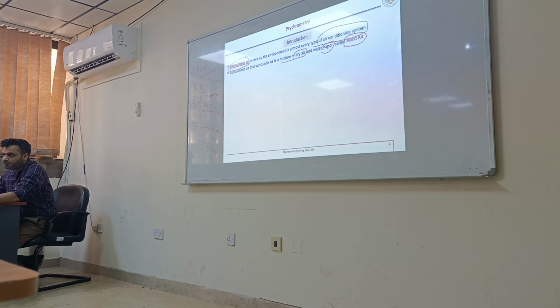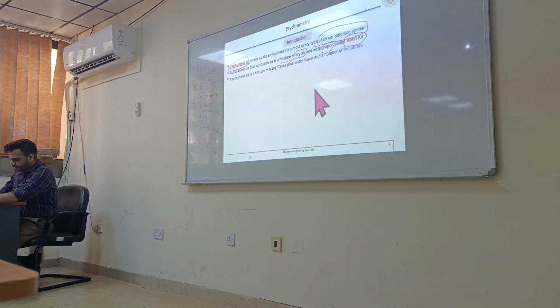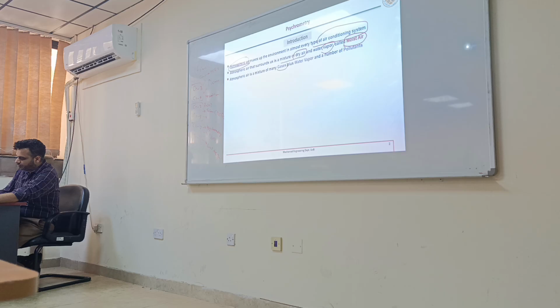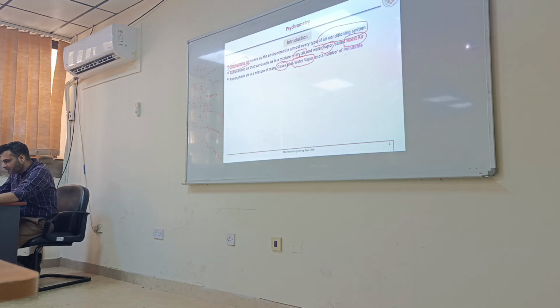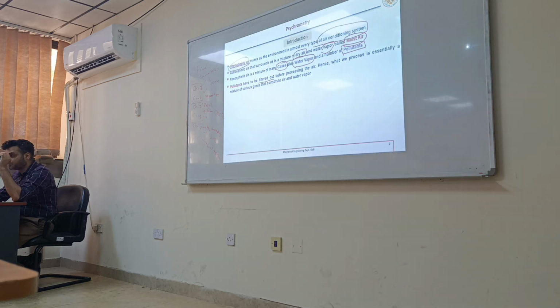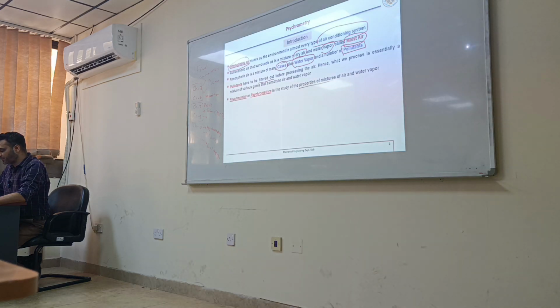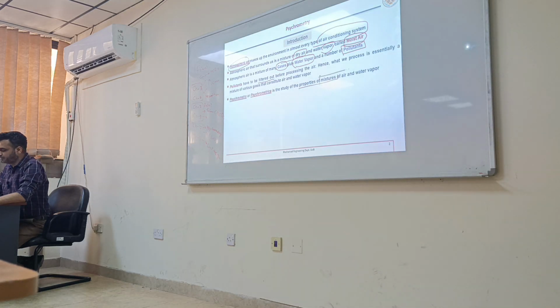And technically, we should call it moist air, right? It's not perfectly dry. It's not all water, of course. So it's a mixture. This atmospheric air actually consists of a mixture of gases, which is air plus water vapor. And of course, there are pollutants in it also, dust particles and other unwanted material. And these pollutants we must filter out, right, before sending this air into the room to be air conditioned. So psychrometry, or psychrometrics, is the study of properties of this mixture of air and water vapor.